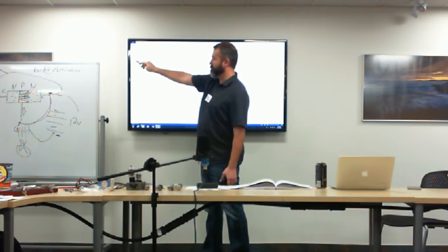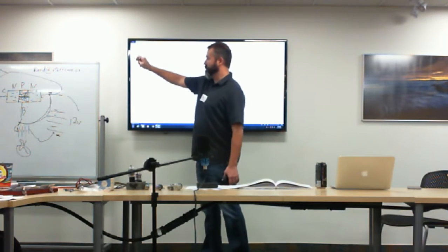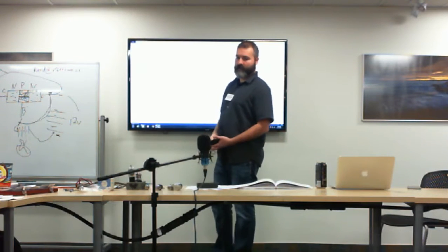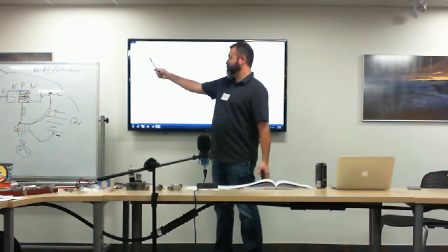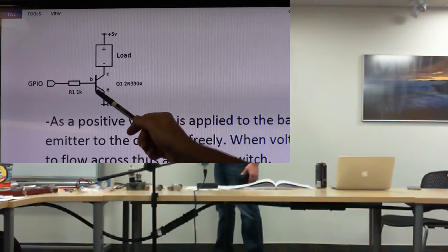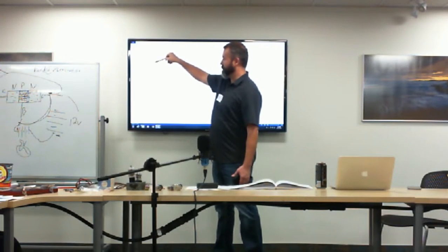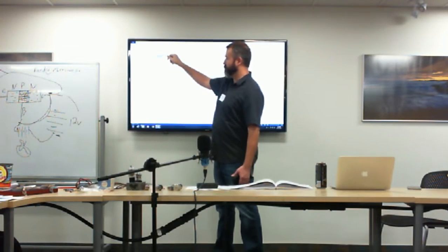The 0 is grounded on the negative of the Raspberry Pi in this example. So when I tell the Raspberry Pi that I want to turn on the fan, it's going to put 5 volts across the base of this NPN transistor, which is going to forward bias the emitter, causing electrons to flow at a maximum amount, allowing the full 12 volts to control my fan.